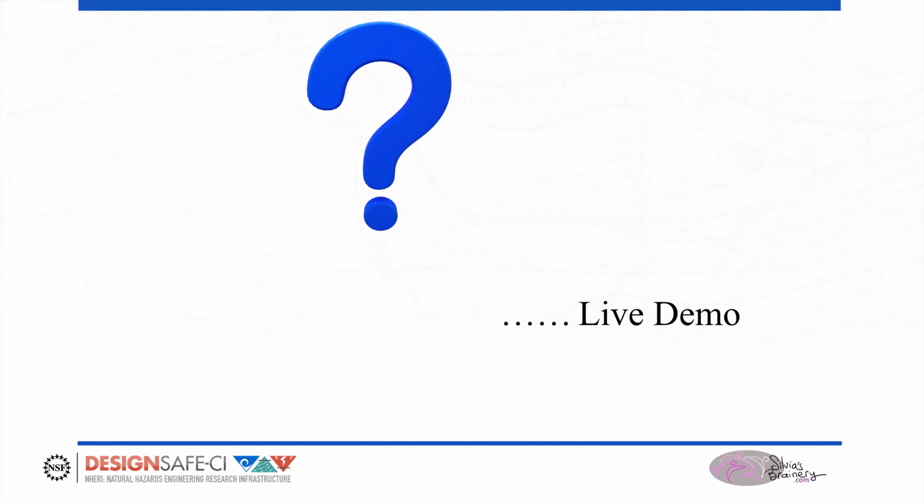Yes, you can. Of course, you write the recorders. You have to tell it what everything is. Somebody in Abaqus wrote a script that it runs internally that outputs everything. In OpenSees, you would have to write it all out. I think the MPCO recorder does that, and it may do it efficiently because it uses an HDF5 file. But my recommendation is just be careful, because as I said, the output takes time.